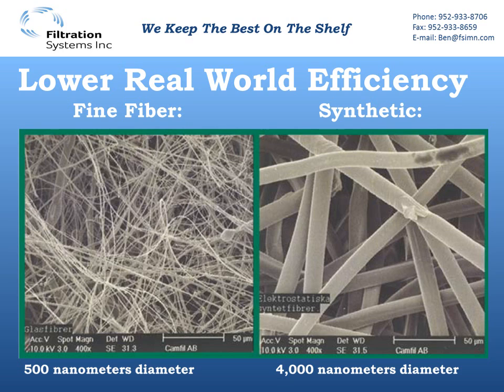You can also see all the open space in the synthetic medias. That's why the initial statics are lower. But again, not only is the square footage of media lower, the actual amount of media within itself is lower. Those coarse fibers, there's just not as much fiber there.